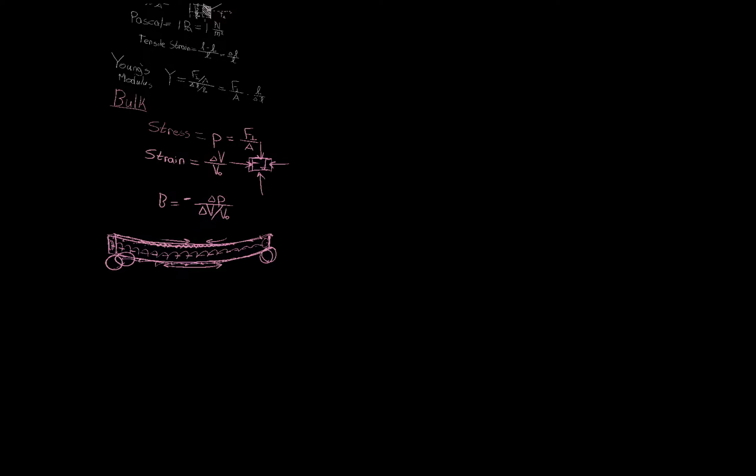But check out the most common building unit, the I-beam. Right? Familiar with this thing, the I-beam? Look at the shape of that. It's almost exactly what we just discovered for what a material would need to resist compressive and stretching stresses on the material. You don't need anything in the middle part. You can cut it and save weight. But you need reinforcement here and you need reinforcement here, right? And it kind of tapers because the closer you get to the center line, the less reinforcement you need.